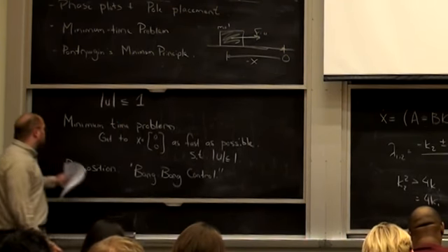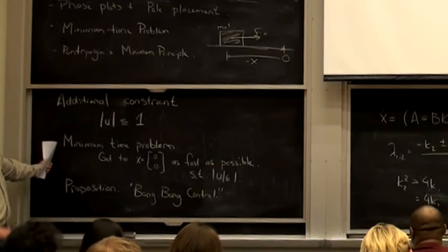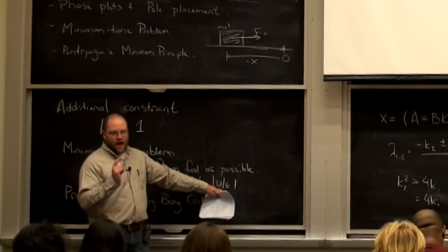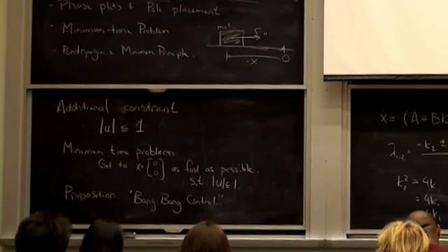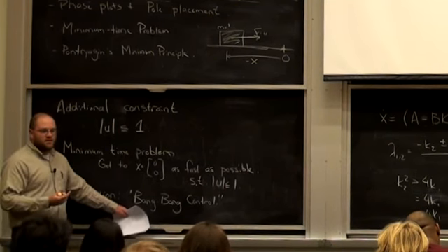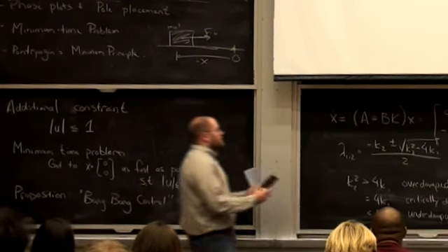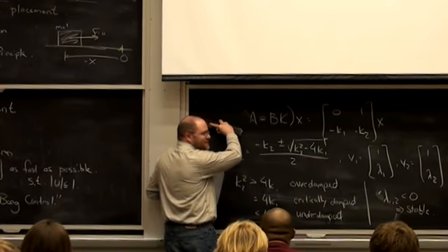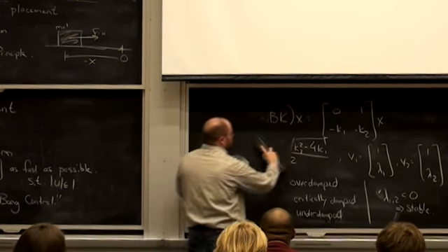Okay, bang-bang control. You might hear people casually say bang-bang control is optimal, and it's very common if you have hard limits on your actuators. It's very common that the best thing to do is to be at those limits all the time. If that's the way you've defined the problem, bang-bang control solutions are pretty ubiquitous. They don't always work that well on real robots because actuators don't like to produce max force and then negative max force within a single time step.